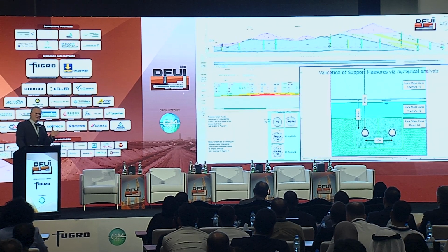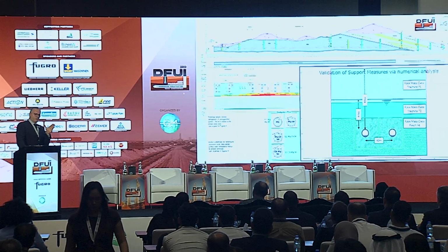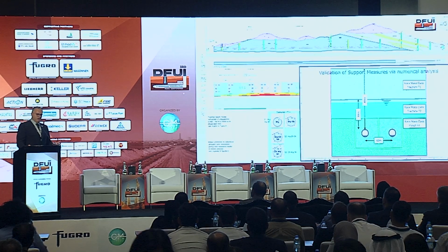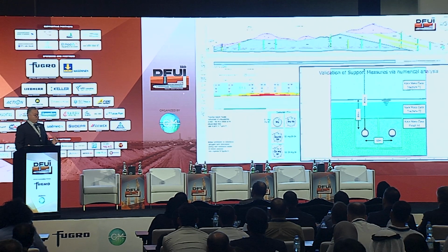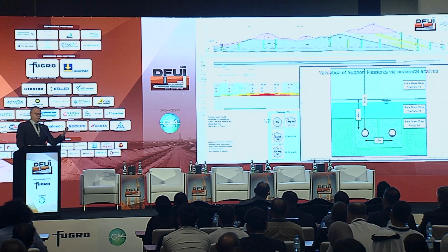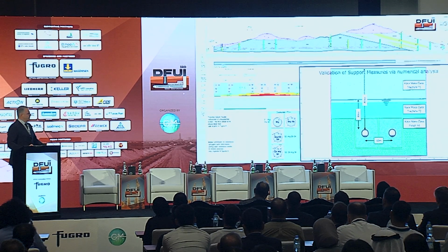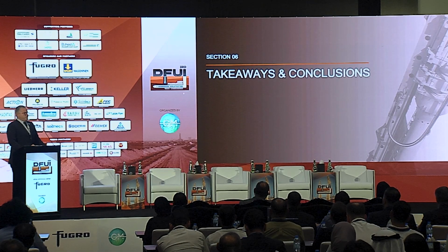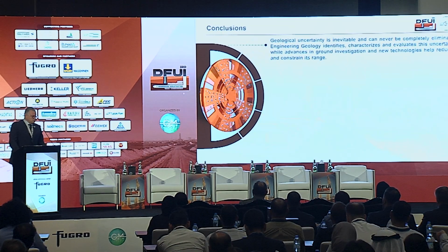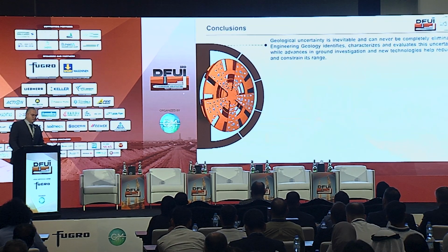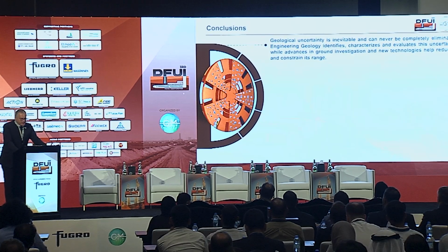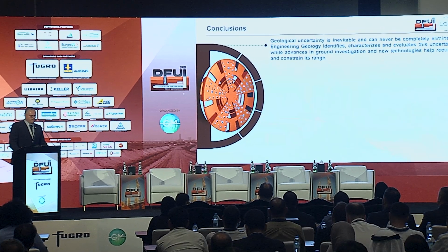So you follow exactly the same path, but before using rock mass classifications blindly, you also know how your rock mass type will behave in a given stress environment, in a given hydrogeological regime. Of course, geological uncertainty is inevitable and can never be completely eliminated.